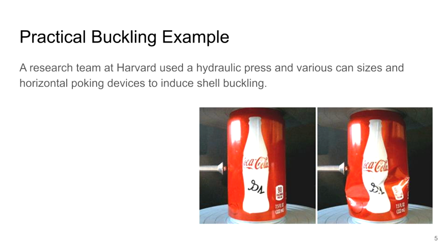Here's an interesting example of buckling in soda cans. Have you ever seen the party trick where a fully grown person can balance on an emptied soda can? Even though the can's wall is only 0.1 millimeter thick aluminum, it can sustain the load as long as its shape is perfectly cylindrical. The axial stress is below the yield stress, which is easily checked by dividing the force by the cross-sectional area. However, if you press lightly against a point on the cylindrical surface, the can will buckle